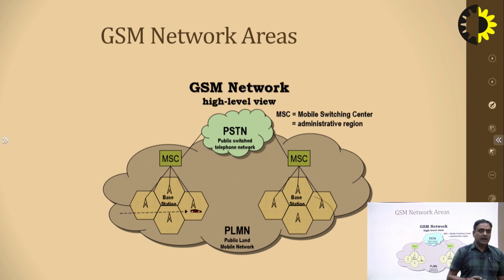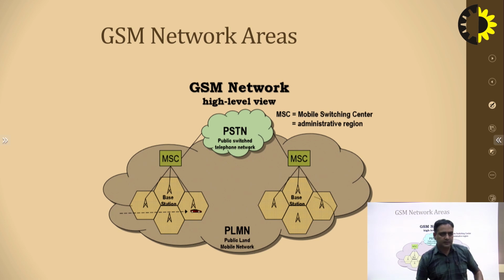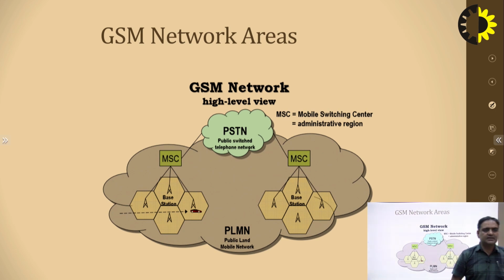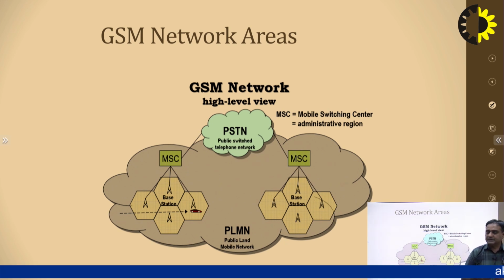capture the signals from all the MS, all the mobile stations or mobile equipment which is under this particular BTS or under this particular cell ID. So this BTS is responsible to capture the radio signals and transmit the radio signals. That is why it is known as base transceiver system, it transmits and also receives the radio signals. These BTS are connected to the BSC, base station controller, and all these BSCs transfer the information to the MSC, mobile switching centers.